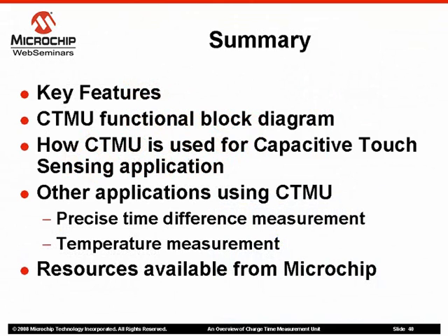So this concludes this webinar. To summarize what we discussed so far, we have seen the key features and detailed block diagram of CTMU, and how to use CTMU for capacitive touch sensing and TDR or time domain reflectometry, and how to use CTMU for temperature measurement application are discussed in this webinar. Also, the resources available from Microchip are discussed.